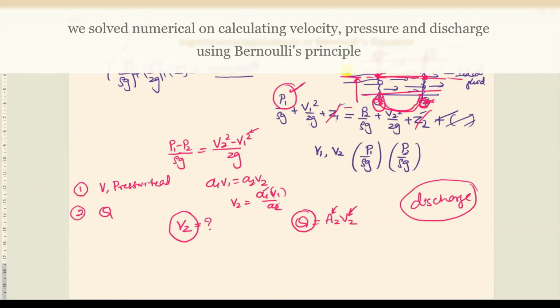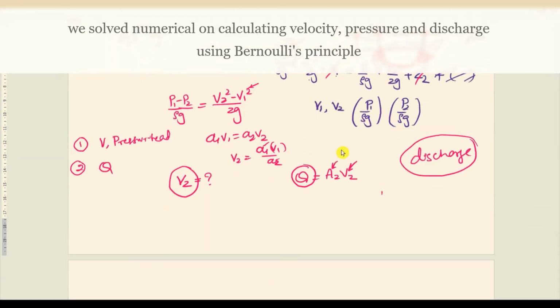Now, what are the practical applications of Bernoulli's equation? There are some devices which work on the principle of this Bernoulli's equation. For example, the devices are Venturimeter, Orificemeter, notches, nozzles, etc. So these are the devices which are used for measuring the discharge or quantity of water flowing through a